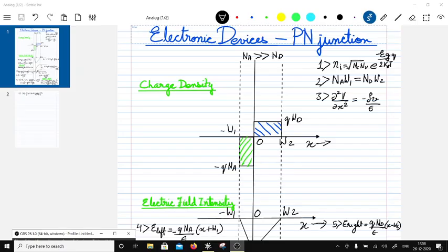And this PN junction, we started with the semiconductor, with intrinsic carrier density, right? Then we doped them, and when we put N and P type together, they form a PN junction, and the charge neutrality is conserved here, right? This is because of diffusion current, which we talked about, and the Fermi levels lining up, right?